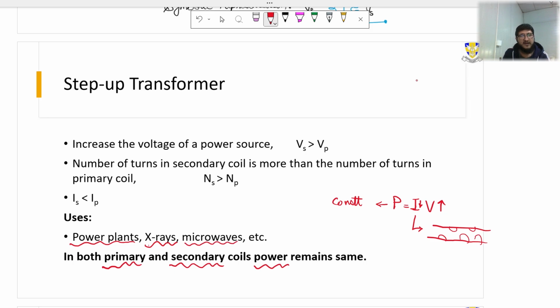माइक्रोवेव में भी यही होता है कि आपके माइक्रोवेव ओवन के बैक साइड पे लिखा होता है that it's going to operate at this voltage. तो हम क्या करते हैं, there is a step up transformer inside the microwave which is basically converting your 220 or 230 volts into roughly, mostly the microwaves are roughly of 400 volts. ठीक है, इससे ज्यादा होते हैं, I think 600 भी होते हैं, 800 भी होते हैं. So that's a way, basically that's a phenomenon behind the step up transformer when we need to increase the EMF.